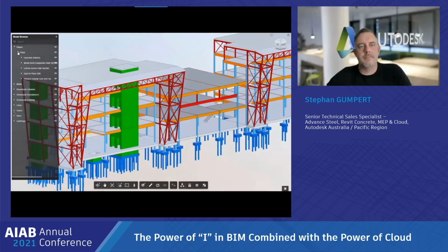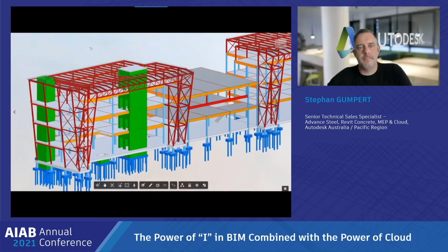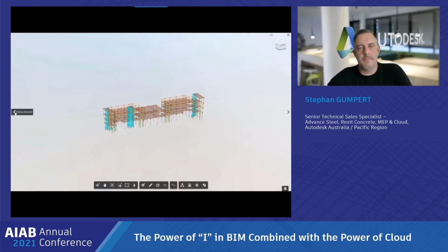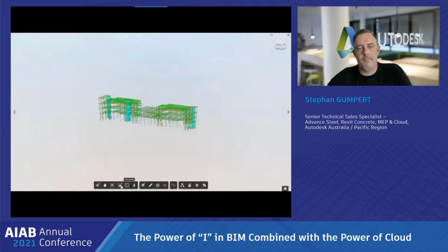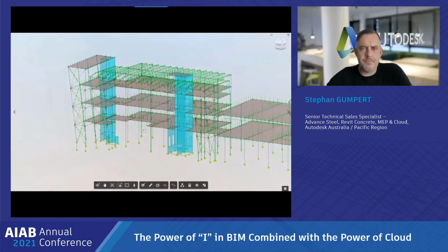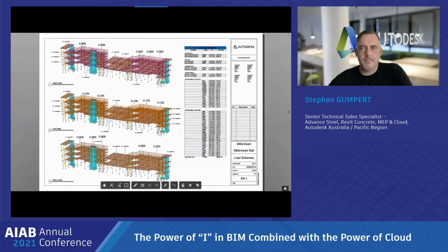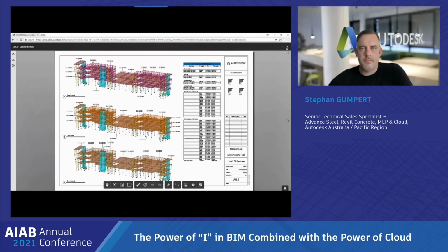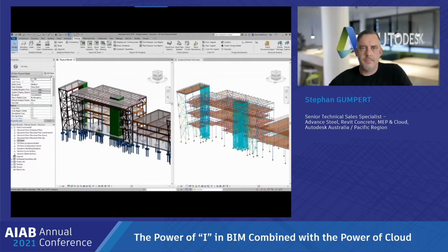When project teams have the right information at the right time, work happens faster. BIM 360 Docs lets them publish, manage, review, and approve all drawings, documents, and models, anytime, anywhere. The project teams can not only review all information, but they can also download project files. Having access to the project data, a structural engineer continues the design process, performing structural analysis and running code checking optimization. The Revit analytical model can be sent to Robot Structural Analysis Professional with all the information needed for structural analysis, including boundary conditions and loads.